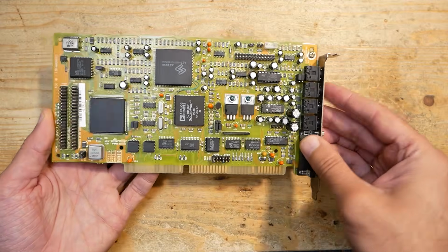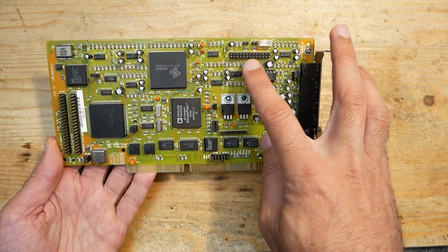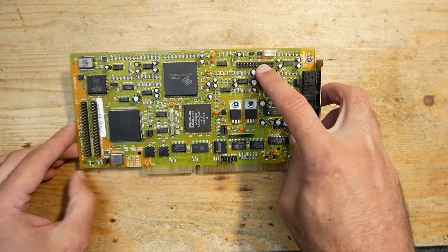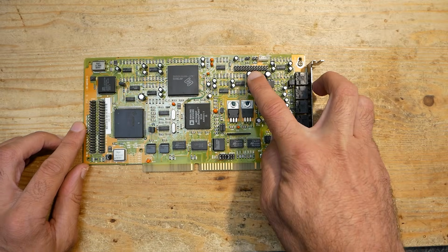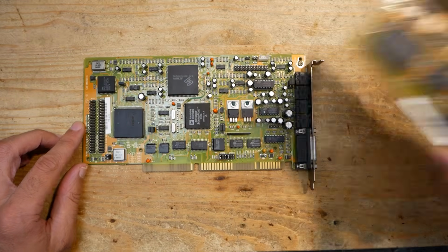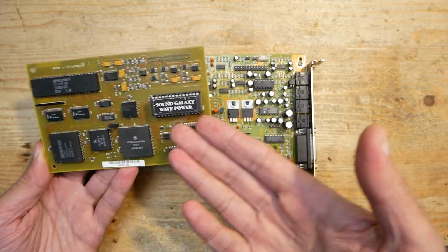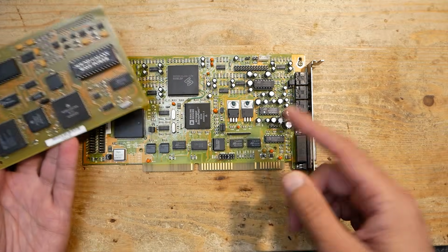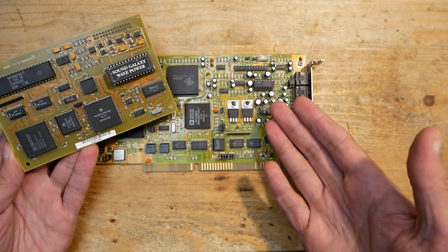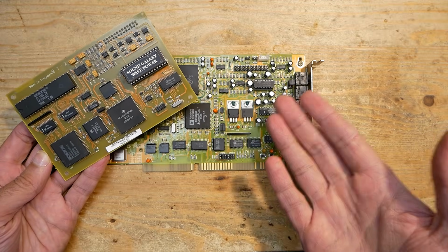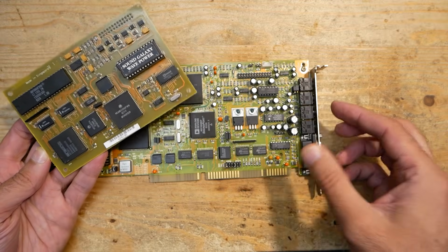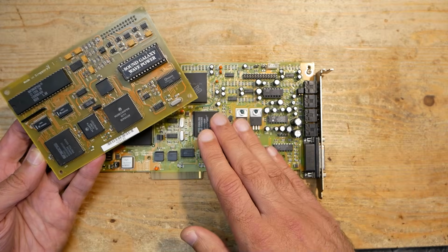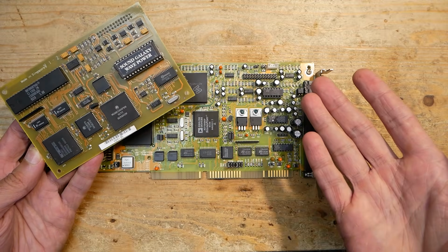Since it is such a versatile card, I was hoping to get a wavetable working on it as well. The wavetable header has a standard pinout, so the hopes were high. For the experiment I used the Sound Galaxy Wave Power wavetable, but I was not successful because this sound card unfortunately does not support the MPU-401 MIDI standard, and so no General MIDI was possible. I tried other wavetables and also SoftMPU, but that didn't work either.